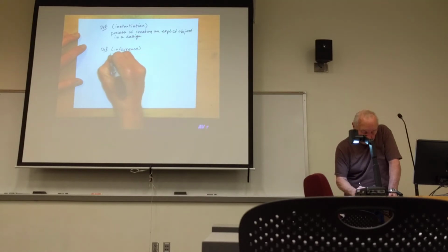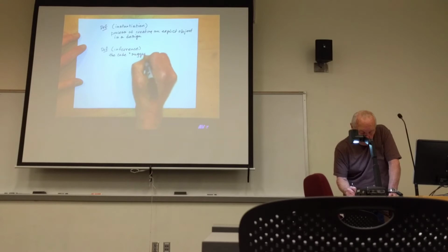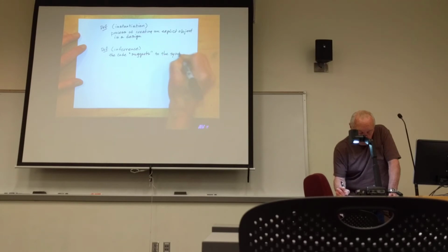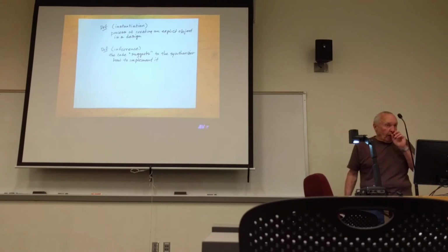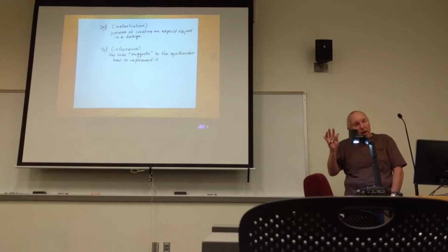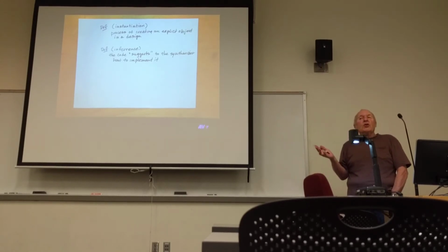Inference. If you are inferring something, what you're doing is you've coded up your description in such a way that it makes a suggestion to the synthesizer on how to implement the circuit, but you're not telling it exactly how you want it implemented using specific hardware devices.